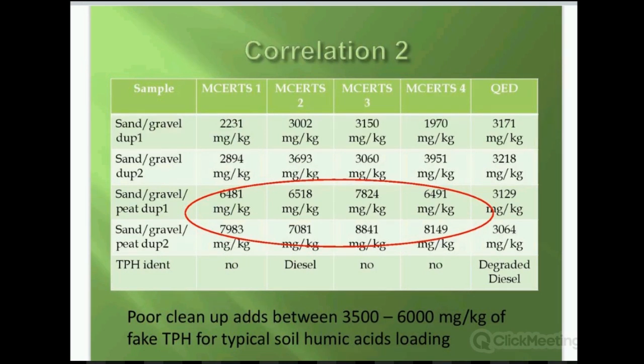Now, if that was sand, just pure sand, or any soil with that amount of peat in there, automatically the lab results would have actually pushed that into the hazardous category under WM3, and you'd have been disposing of that as very expensive stuff to dispose of, when in fact it is unnecessary to. It is not TPH.